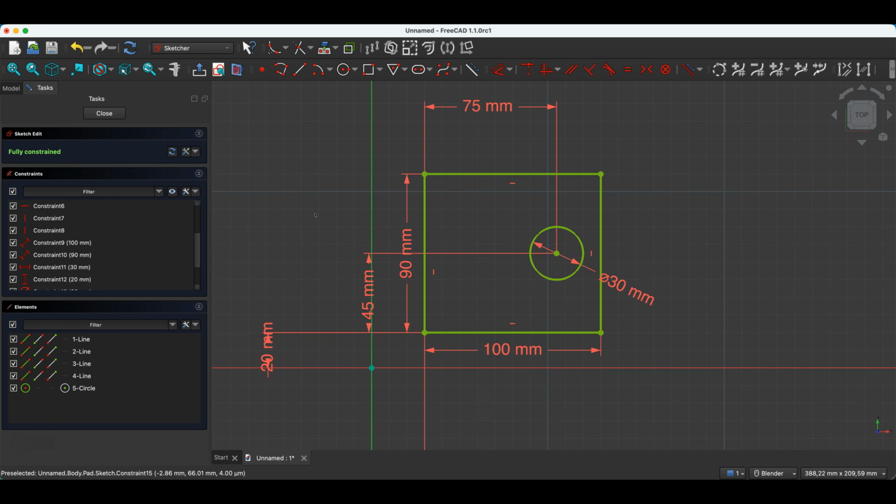Dimensional constraints define one fixed, specific position. We define a specific distance between geometries, but as you can see, cases may arise where a dimension might be changed. Then it is better to apply relations between geometries and specify that a point, for example, should lie between 2 points, and this should be done independently of the geometry dimensions. I will show you how to do this on this example.